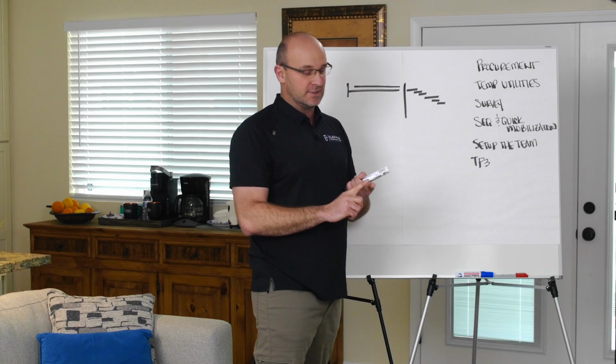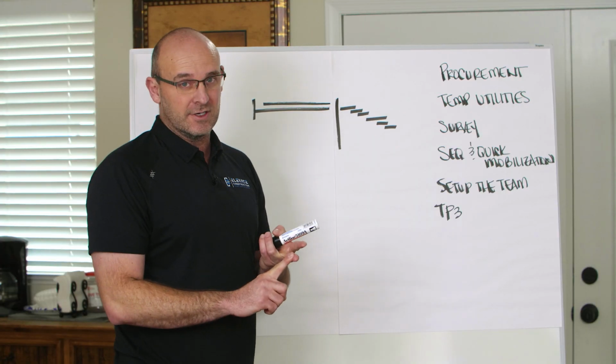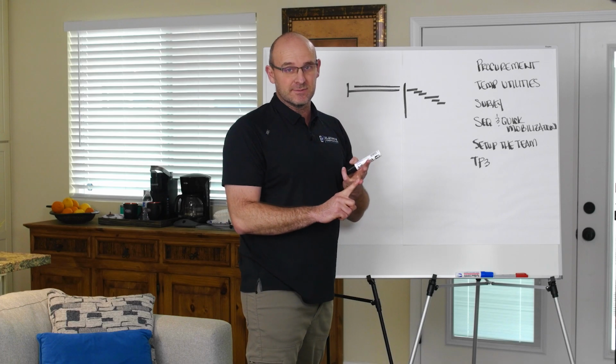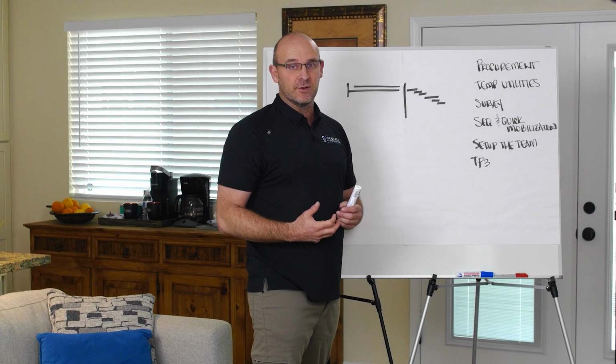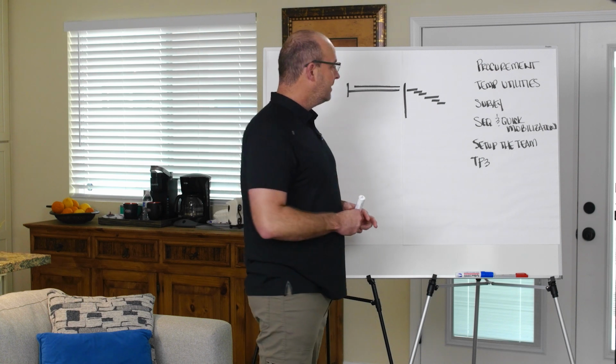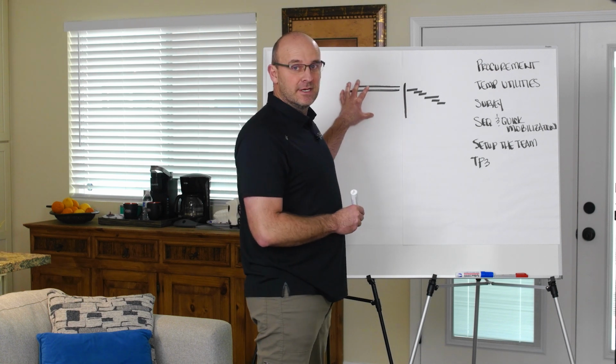So that's why I love pre-construction efforts, is because you can go ahead and get deferred submittals for the post-tension out. You can get your detailing for your concrete structure going. You can get your shoring systems designed and get those shop drawings going through and get them approved, right? Anything that you need here needs to be done in pre-construction.